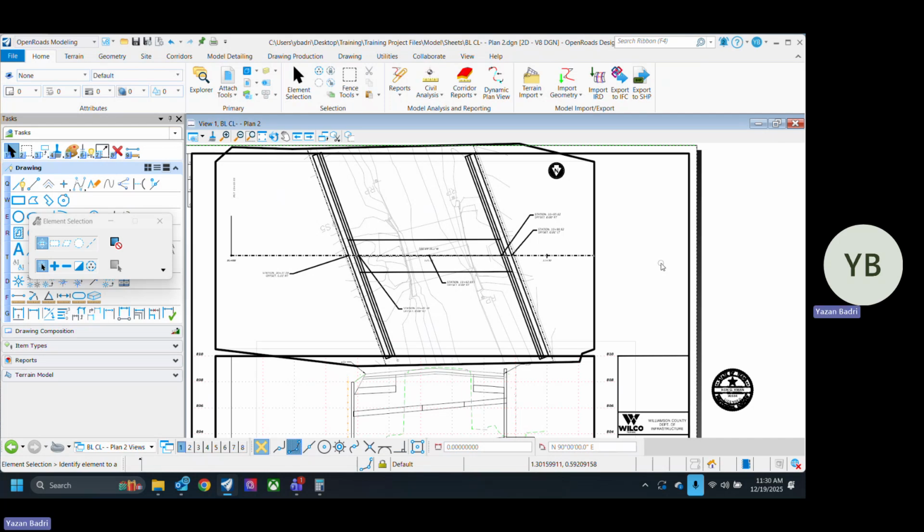Usually, if your road is going south to north, you cut your sheet this way, placing your culvert alignment left to right. But here we did north to south, so I did the alignment right to left, which is why the north is upside down.